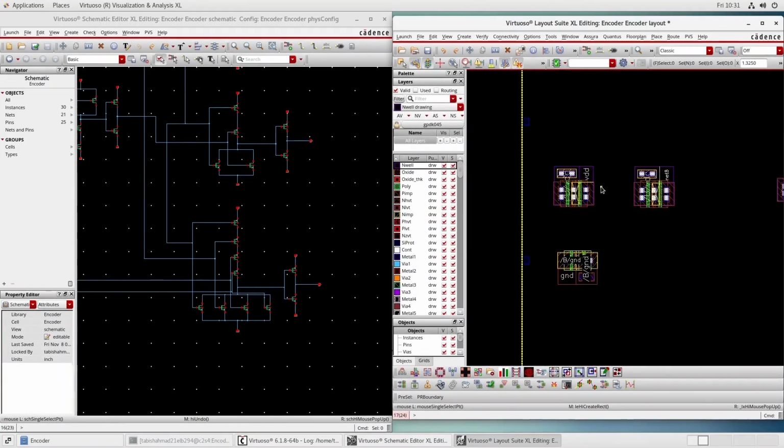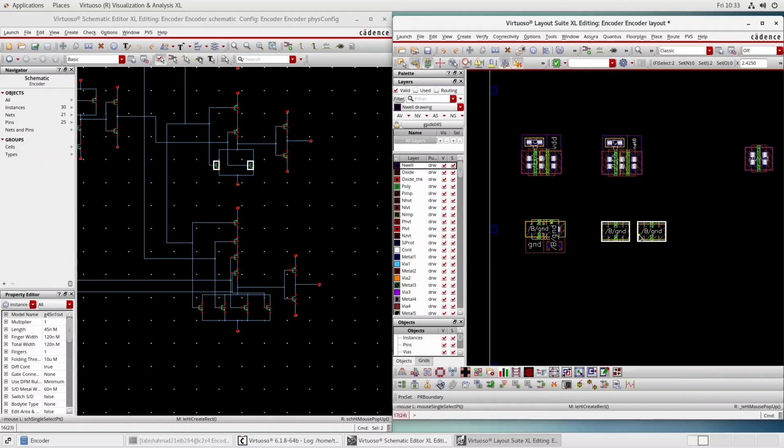Remember to press Q or right click on the PMOS to go into the properties, then go to the body type, then make it detached, and if it is PMOS then do the top tab, if it is NMOS do the bottom tab, and then you can get this NWell and PWell for respective NMOS and PMOS.